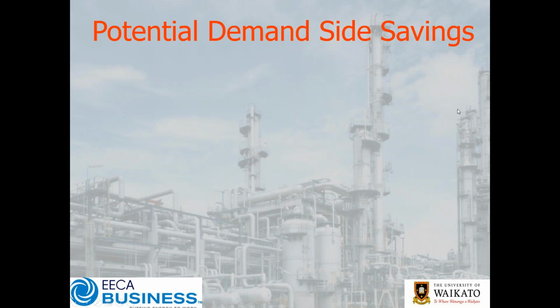So to really get stuck in today, on the demand side, in looking at what our potential is, number one, top of the list, is air leaks. It's become a cliche. Everyone knows that air leaks are an easy win, yet the irony is it's a bit like common sense: it isn't always as common as you might think. Just because we know air leaks are an easy win doesn't mean that they always get fixed, and indeed many sites will start with a hiss and a roar, get on top of their leaks, but of course they keep coming back.